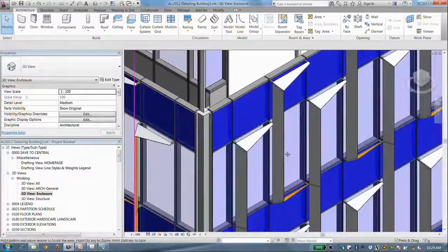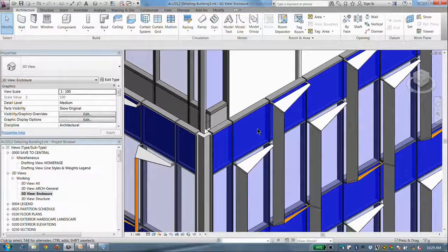To get a sense of what's happening here, for the enclosure, there are basically 2 sets of Revit curtain walls. One set is the actual enclosure wall with the glass panels and the opaque panels. And down below, there's actually perforated panels where the parking garage is. And then there is a second set of curtain walls wrapped around the inner set, the enclosure wall. The second set are these solar fins. The solar fins are panels. They are Revit curtain wall panels in the shape of fins. There's no glass panel or anything like that. There are no mullions on this second set of walls.